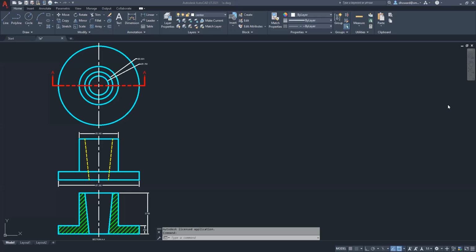All right, so this is what we're doing. As you can see, we have the top view of part 21, the side view of part 21. And here is what's new, the section view, right underneath the side view. It's as though we just cut this thing in half, right? Right on this red line.